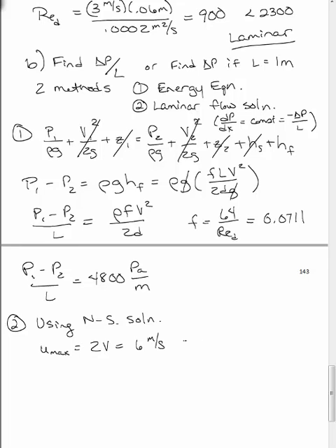And that is U at r equals 0. And there's a number of ways to use this, but if I just use the Umax equation, which we already figured out, that's equal to minus R squared over 4 mu times d/dx of P plus rho gz. Well, notice this rho gz is inside the d/dx.